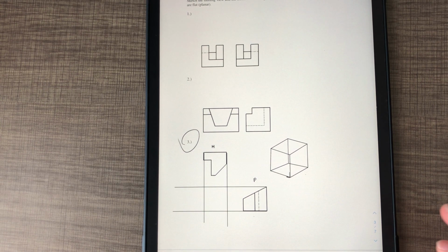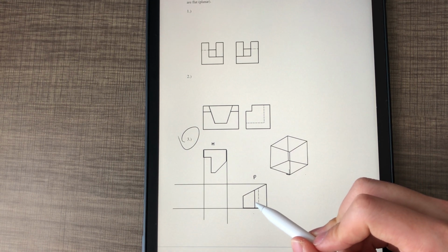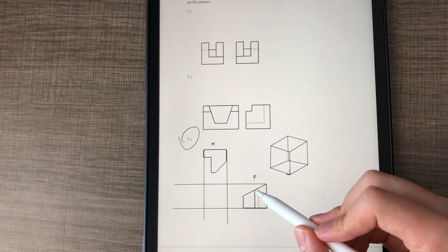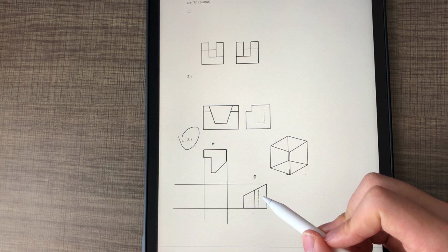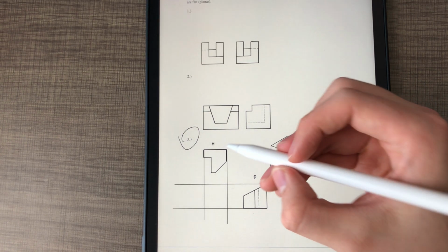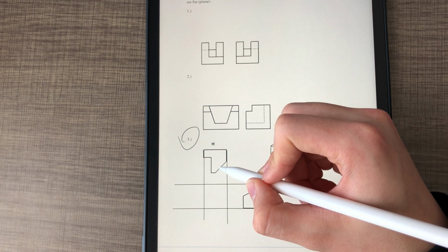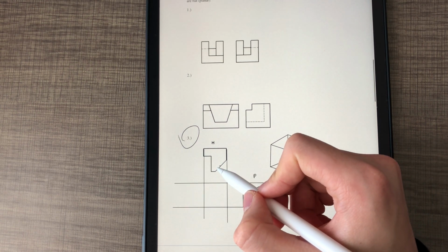It's a little bit rough, but we can actually start to take some features. So one strategy that I like to use is in a missing view problem, every time I see a completely enclosed box, as in enclosed by all visible lines, that means it's a complete plane. Or every time it's enclosed and something separated, that means it's a change in plane. So over here, I have 2 changes in plane, here and here, right? That corresponds to, on the horizontal plane, or from the top view, here and here, right? So I have a change of plane here to here, change of plane here to here.